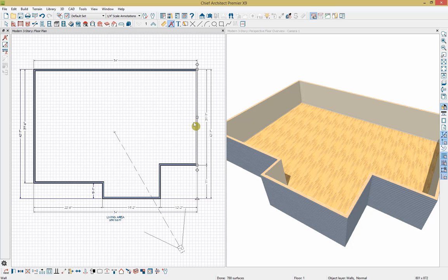So we're adjusting the wall that we select. I'll single click on the parallel dimension to that wall, and we're going to tell the wall to lock this end and extend this bottom end, which you can see by the little indicator here. You can modify that to act a little bit differently if you'd like. We're going to change that to 34 feet. So I'll put the foot marker in there.